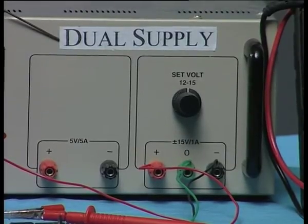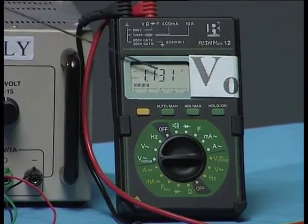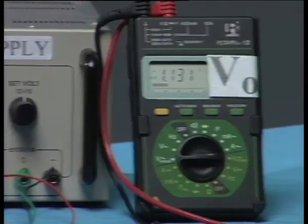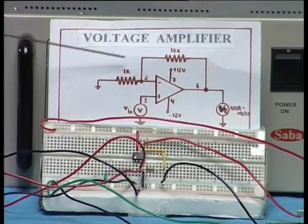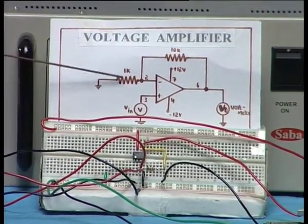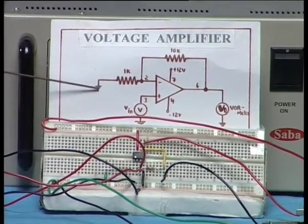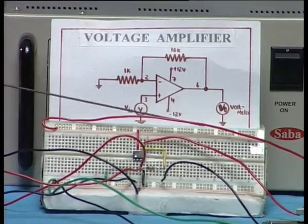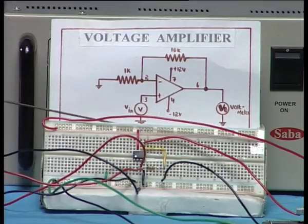This is a dual supply, and you also have one more multimeter which is for measuring the output voltage, that is why it is called V output. So you have the circuit here, and to clarify I have given the circuit also here in the circuit diagram. You see here it is exactly the same non-inverting amplifier. The minus input is connected through R1 to the ground, and the R2 is 10K connected to the output, and this is the voltmeter, and you have the VCC plus minus and the ground connected. This is the voltage source V in that is connected, which is here.